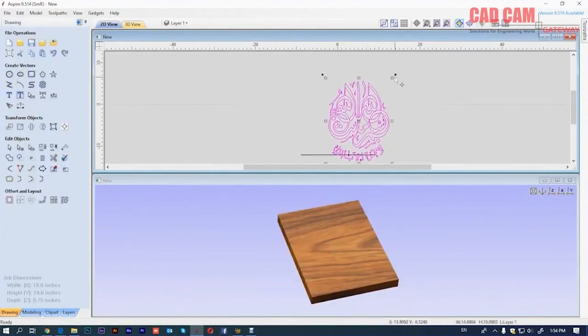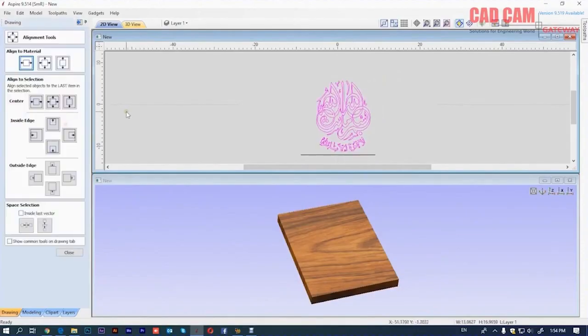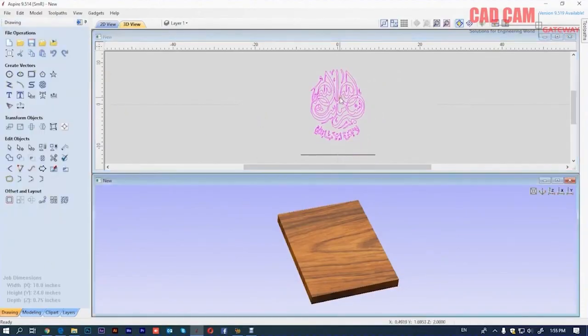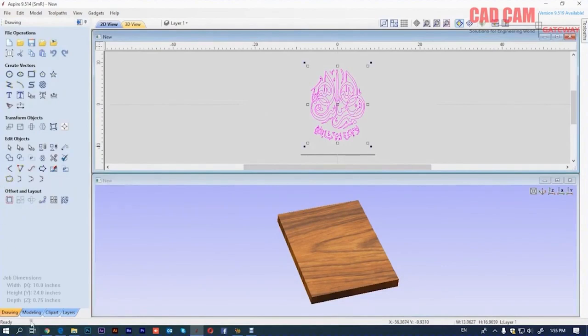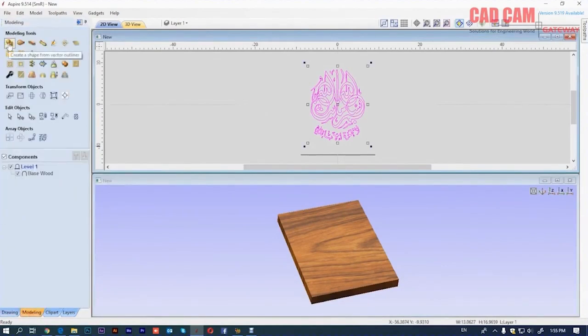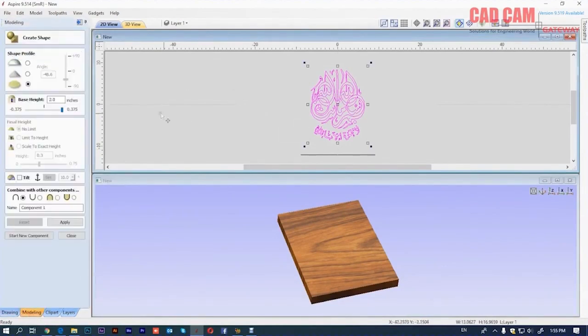Align it. For alignment, I use the align command. This object should remain selected. Go to 3D, here create the shape. As soon as you do this, you set this curve profile. Okay, for the rise, I am setting it to 0.125 here. Let's keep the composite as 1. If you apply it and see, you will notice that effect on top of it.